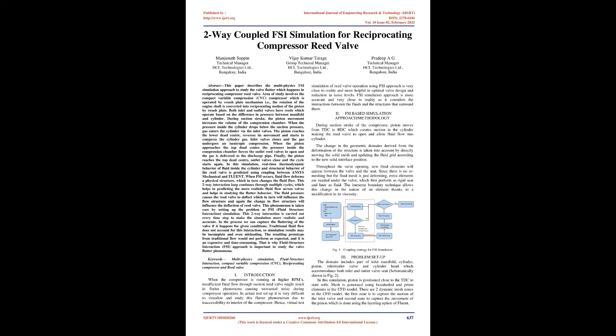This two-way interaction is carried out every time step to make the simulation more realistic and accurate. In the process we can capture the fluttering of the valve if it happens for given conditions. Traditional fluid flow does not account for this interaction, so simulation results may be incomplete and even misleading.